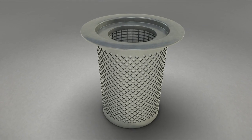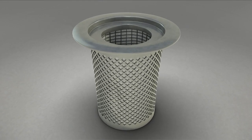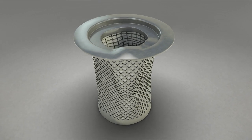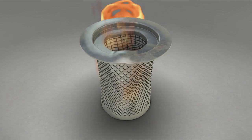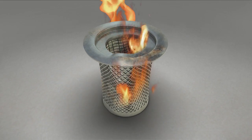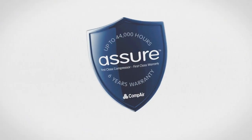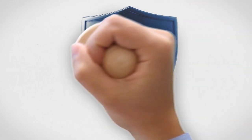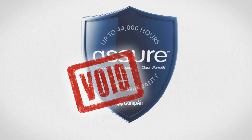In addition, there's the risk of a complete collapse of the air oil separator due to increased pressure differential, or, if the element isn't suitably earthed, a fire caused by static discharge. And don't forget, if something does go wrong, you're effectively on your own. Using non-genuine parts voids your warranty.